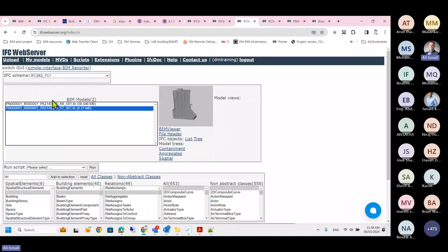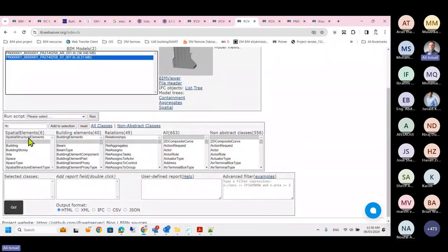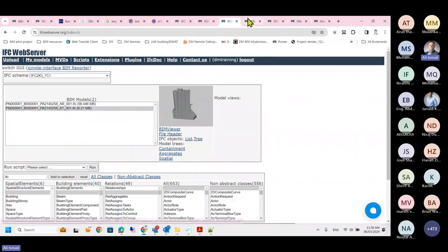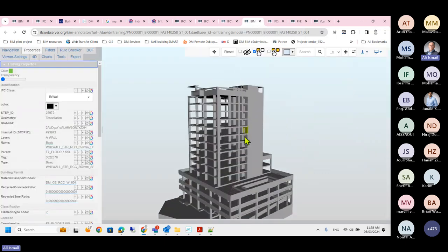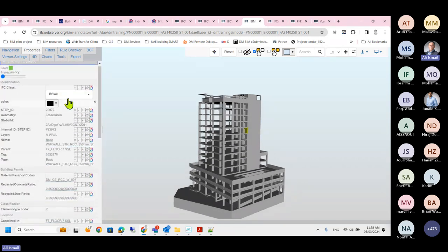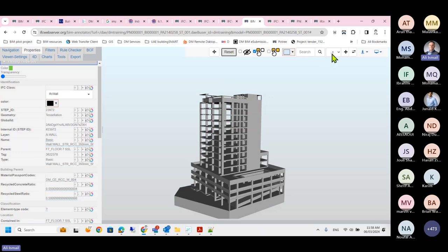Furthermore, with these tools or similar tools, of course, you can get access to any information inside the model. You can also open the model in the online viewer. You can apply many filters. For example, here I have the structural model, and I have the possibility to get access to all attributes, to change the transparency and the colors, and to look at which elements, for example, have geometry that is a tessellation, not parametric. So we have many ways to explore the model, to upload the architectural model, to compare models,